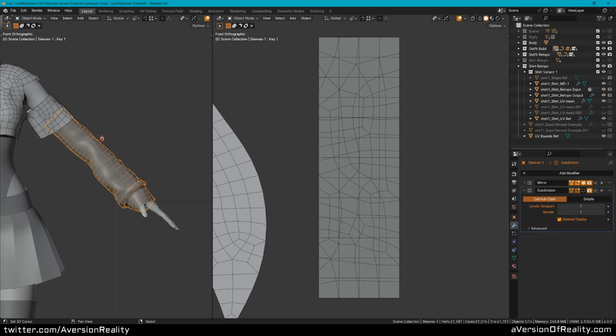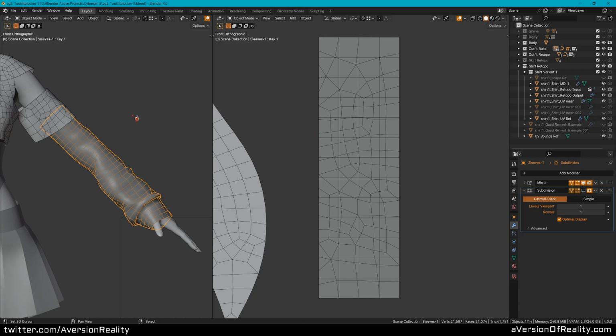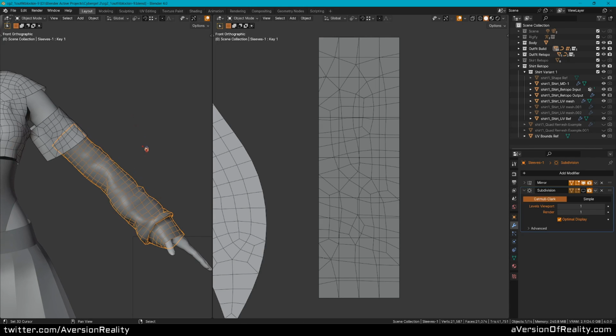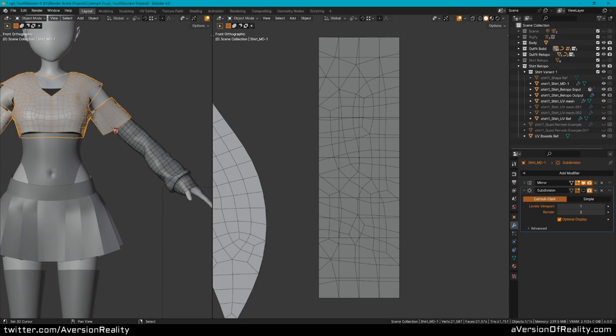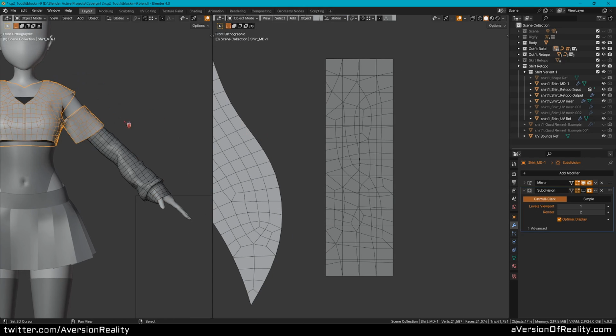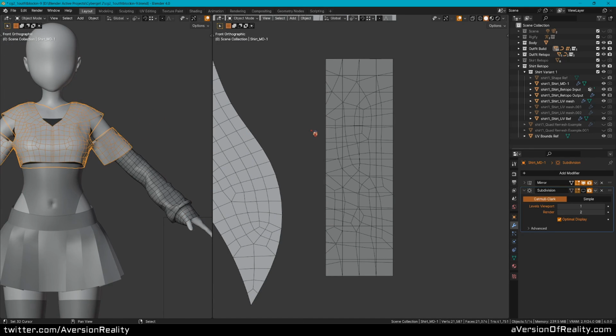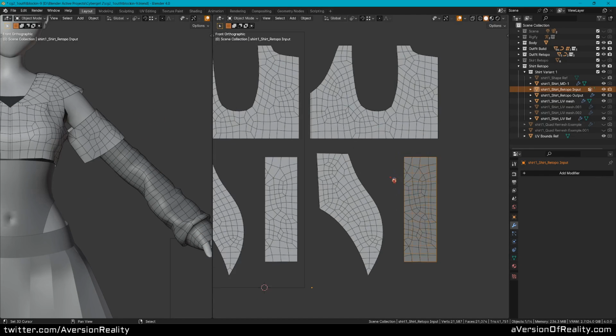But there's still more. I'm also probably going to be using this undetailed version of the mesh for normal transfer, and normals also want evenly spaced quads. So it really is evenly spaced quads all the way down here, except for the detail mesh I'll make from this. Now, what I don't care about too much is the poly count.